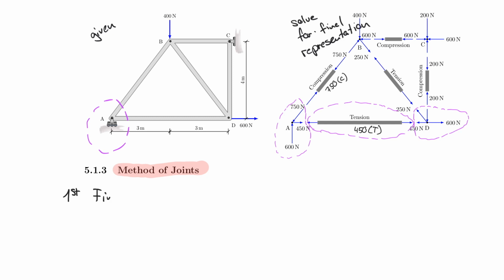is to find external forces, and that translates to support reactions. And I would say find all of them, but in some cases you get away without finding all of them. For a beginner, it's always a good idea to look at all of them first. And now let's think about this, right?